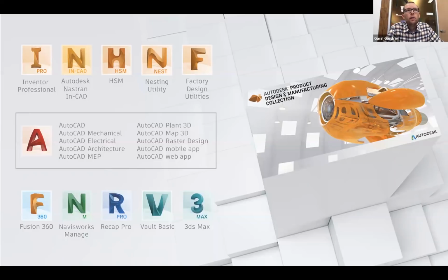Yeah, some of the things that I really like in there, let's say that you go into extrude, you start extruding a sketch and you realize that maybe you're missing a circle for a hole or a shaft. In the past, you'd pretty much either have to accept what you've done in extrude or cancel out, go to the sketch, edit the sketch, put a circle in there, finish sketch, go back into extrude, go back into whatever you were doing, and pick the profile. Now with the breadcrumb, you'd be able to start the extrude command and pick the profiles you'd want. You may realize, oh, darn it, I missed a circle in here. You'd be able to just, in the browser, click on the sketch breadcrumb. It would go into the sketch.